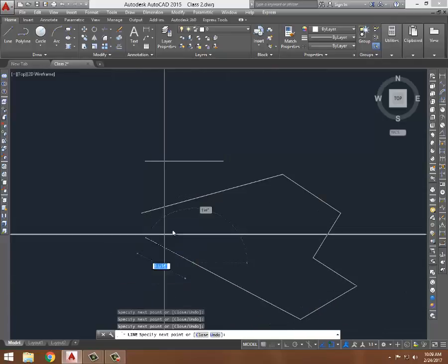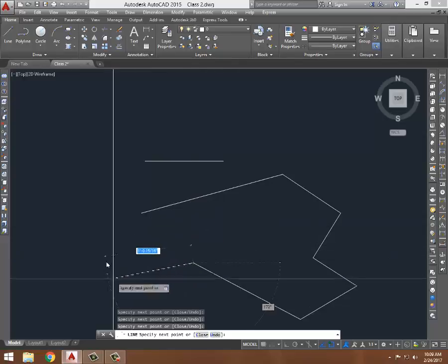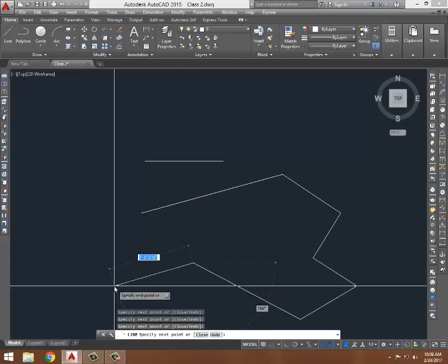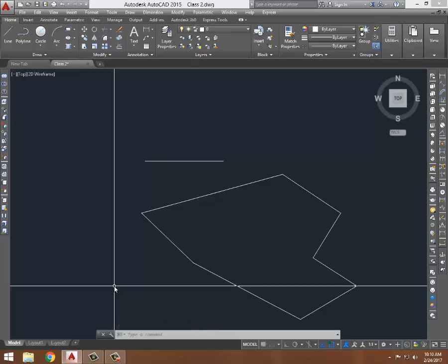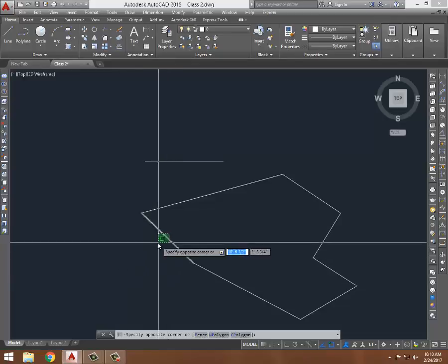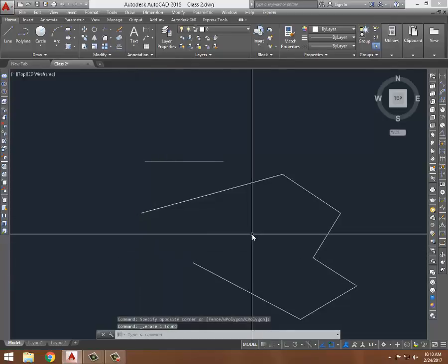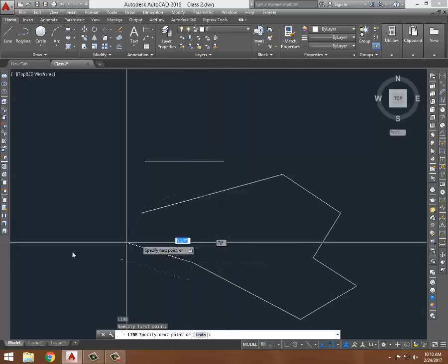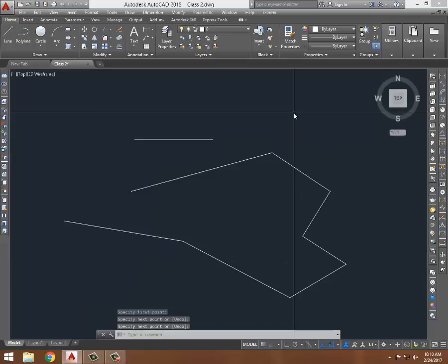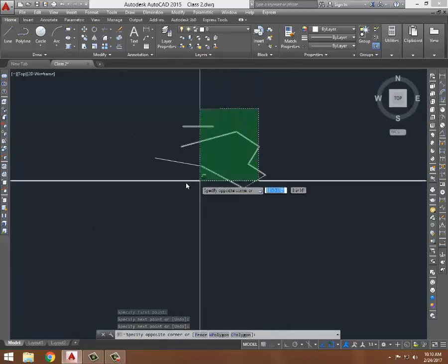Finally, if I want the last point of my line to close with the first point, I can put another one-letter command called C for close. Just C and enter. It closes the line to make it not a rectangle, but an area, we can say. If I don't want to do that, while in the line command I can go anywhere, click and enter, and that's it. It's going to be open. That's how we draw lines.